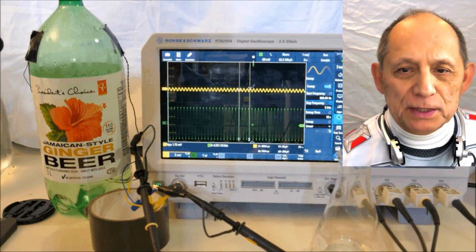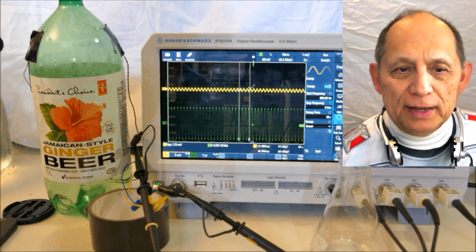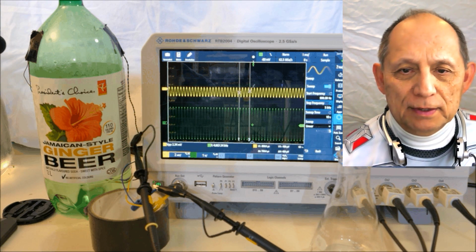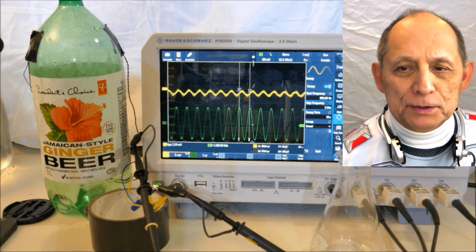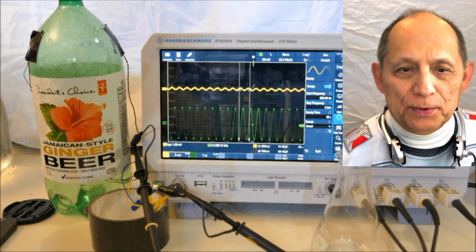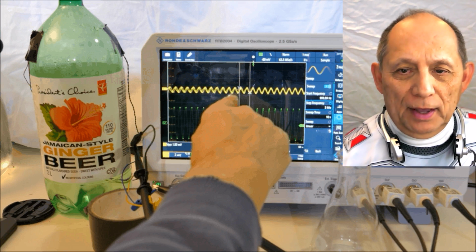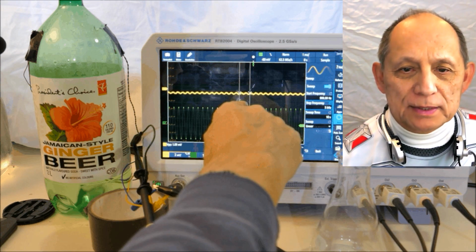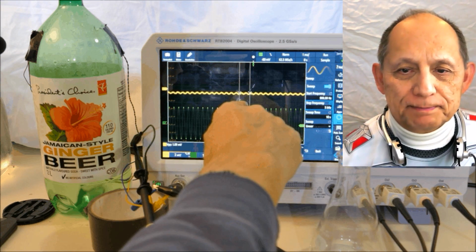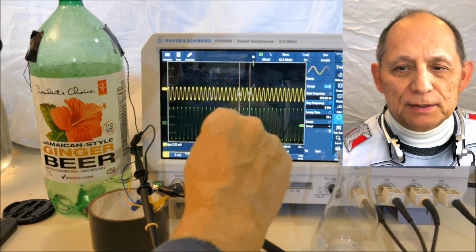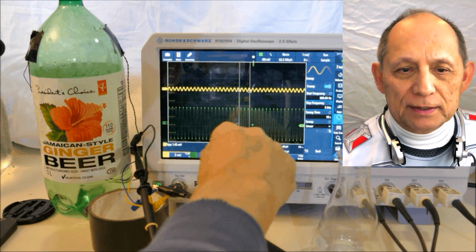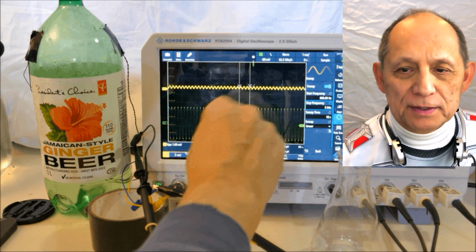The resonant frequency increases as the amount of air in the tank is reduced. This quick video shows a preliminary test setup with a bottle instead of a tank, partly filled with water, and a scope showing resonant peaks as the frequency sweeps. This test used a piezo disc as the exciter and another piezo disc on the other side of the bottle as a sensor.